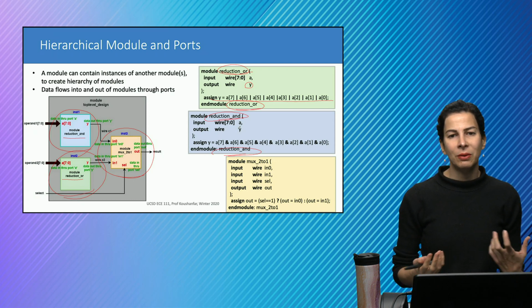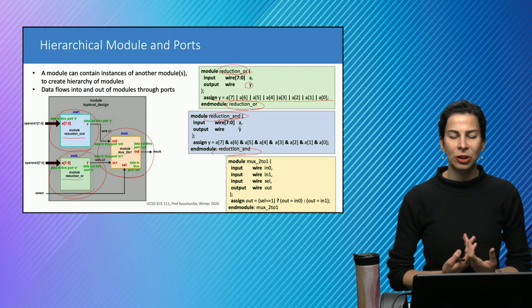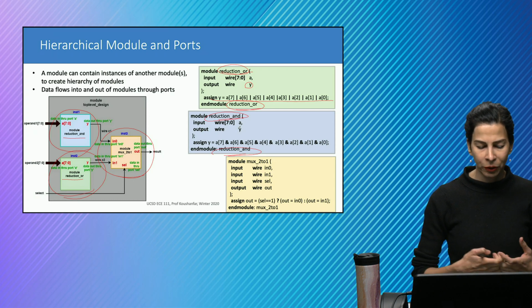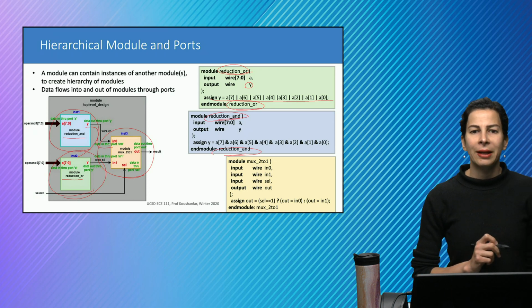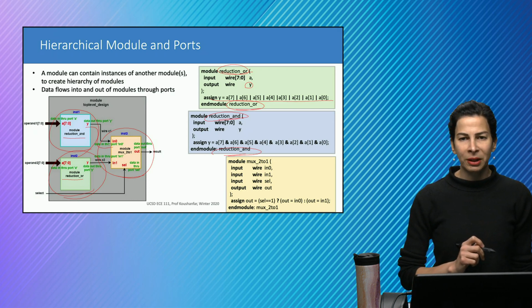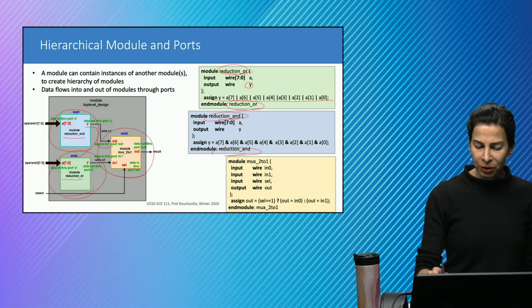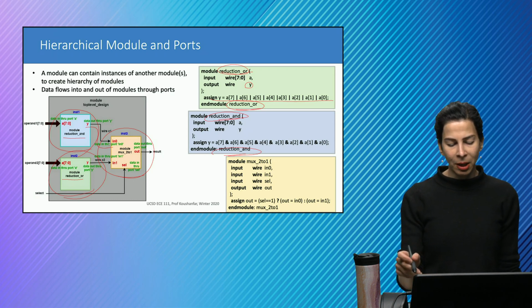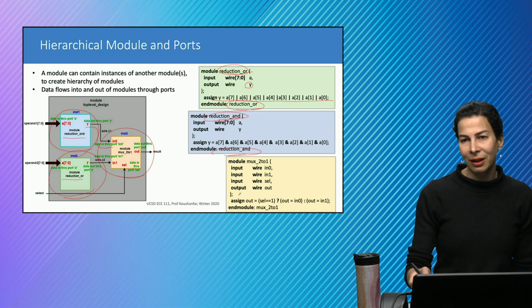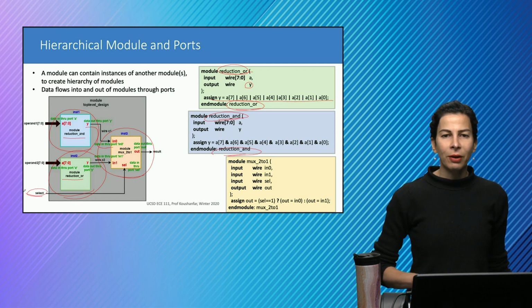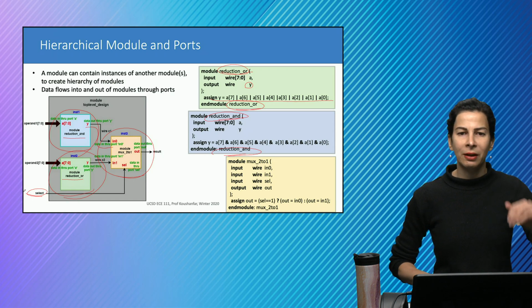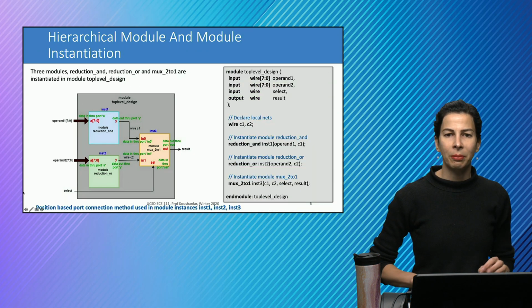But of course, the easiest form is to make sure that whatever needs to come out of this module and is going to the other module is properly connected. On this particular page, we're just defining the MUX module itself, which is basically a selector between the two based on the select signal. Now, if I want to write a higher level design which contains these three modules,